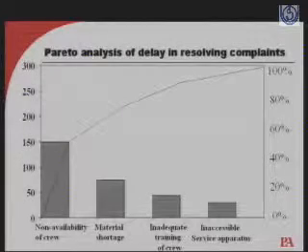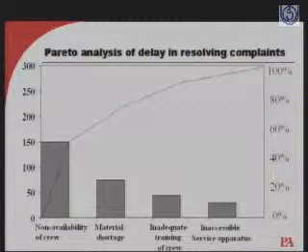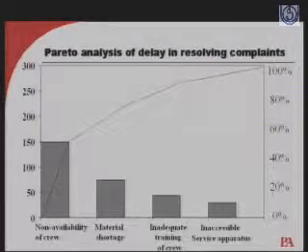So, for example, my meters are failing. Why are they failing? We have to do aging analysis, meaning thereby, the more the age, the more the failure. Is it a fact in case of transformer or meter? At the same point of time, we have to find out what kind of meters are failing. Is it single phase meters or three phase meters, or even in the single phase meters, what are the ratings of these meters? If we do this kind of analysis, we can gain different insights. Based on that, we can develop our game plan to arrest the failure rate of meters or transformers, whatever it may be.